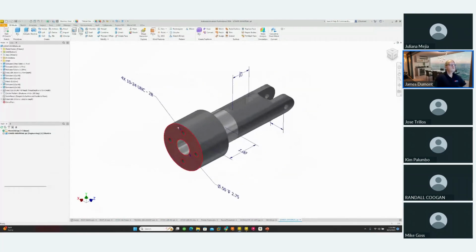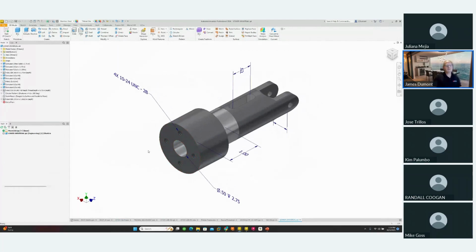So what you can actually do here is place all of the annotations that you would put on your drawings directly on the model, either a part or an assembly. So MBD, there's this huge push for this. And the other benefit is that this information is easily distributable in a STEP file or 3D PDF. These annotations all stay together.